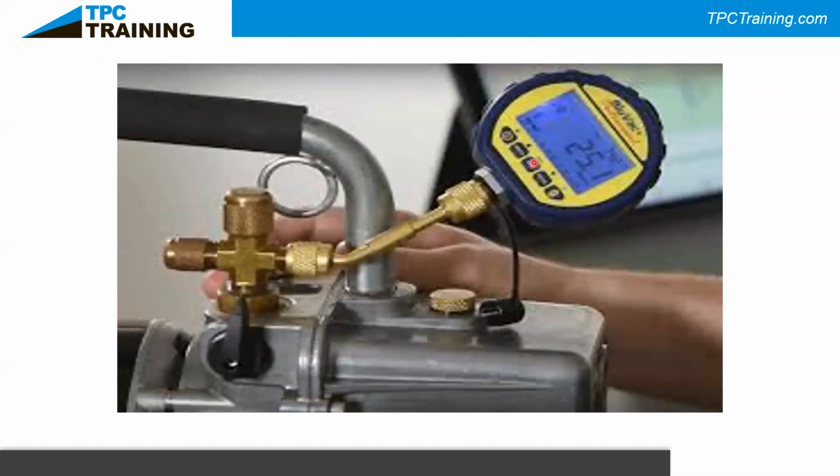The idea is to run this until you see this get down to 500 microns with this isolation valve turned off, without the aid of the vacuum pump. And what we're doing here is we're testing the vacuum pump. This pulled down to 251 because we want to make sure the vacuum pump is working properly. If there's any leaks in this system, or if this cap right here, called the valve, where you're going to put your oil into your vacuum pump, is not threaded in tight, you won't get down to a deep vacuum. A vacuum, again, is anything less than atmospheric pressure. So you're not going to hold it, because atmospheric pressure is going to want to push back into the system, and it's not going to allow it to stay down at that lower level.